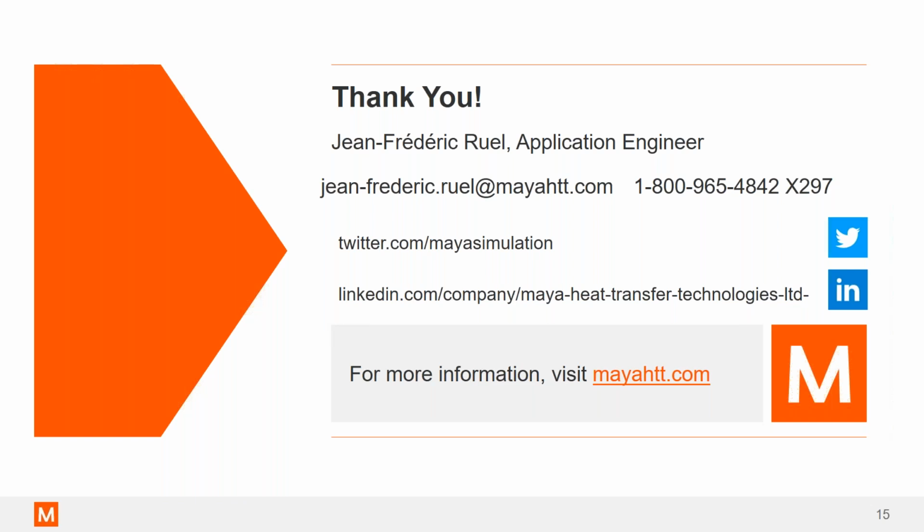You could use what I just showed directly in Nastran, but we also have a dedicated mapping solution that's made for mapping temperatures to structural models. The advantage of the mapping solution is that it has extra constraints and controls over the mapping. And so there's essentially two methods that you can do.